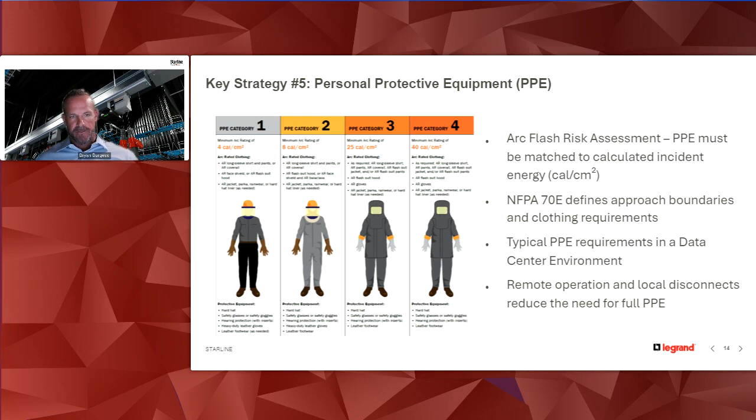40 cal is the absolute maximum. So the only place I could see that in data center use may be on the incoming switchgear. But other than that, you're going to see the other categories at play here. So it could be any of those. And again, it's all dependent upon performing an arc flash risk assessment.